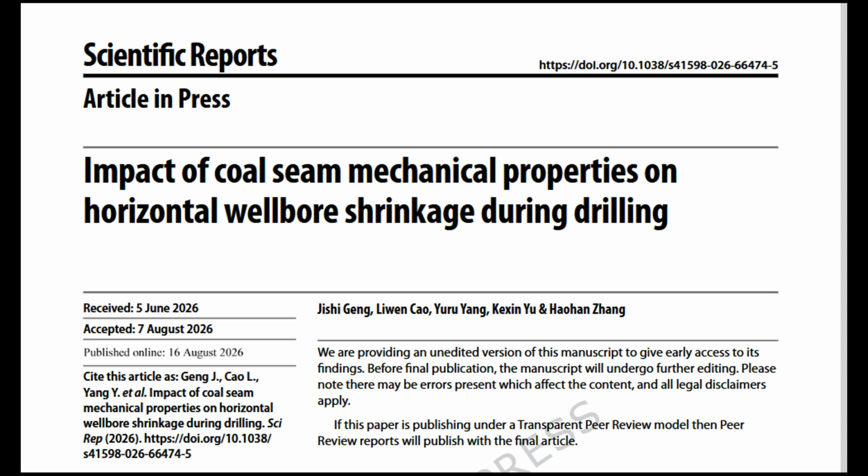Equation 13 defines two important displacements, the inward movement of the wellbore wall and the inward movement of the elastic-plastic interface. The shrinkage of the wellbore is the difference between the initial and current radius of the hole, and similarly for the plastic zone. Equation 14 introduces the non-associated flow rule, which governs how plastic strains develop. It says that the increment of tangential plastic strain is proportional to the increment of radial plastic strain, with the proportionality factor being the dilatancy coefficient.